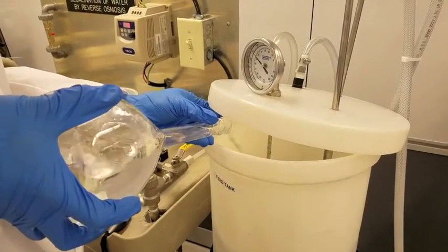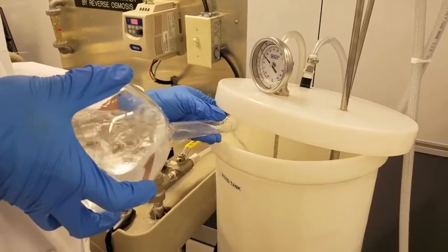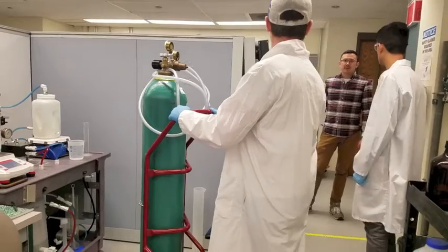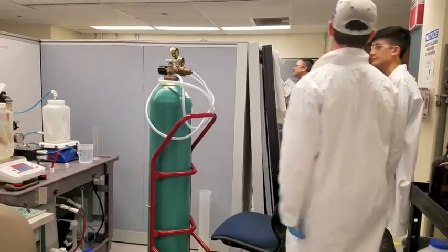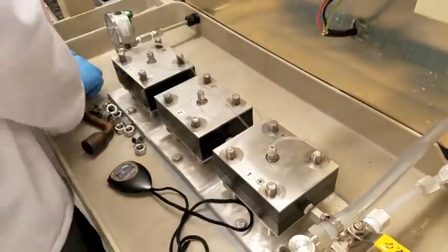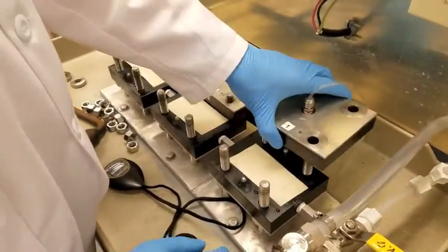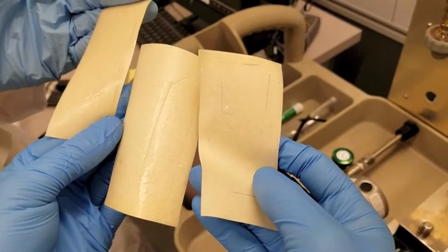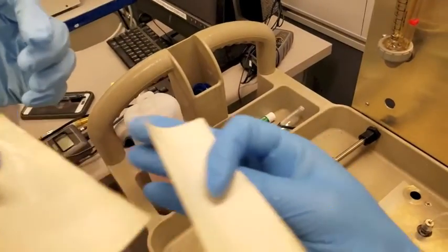Open the bypass valve so that the RO system is connected with the air purge line. Using a compressed tank of air, flow a low amount of air pressure, below 200 psi, through the setup, making sure not to fully connect the fittings. Open each cell and remove the membranes. They can be safely disposed of after examining them for defects.